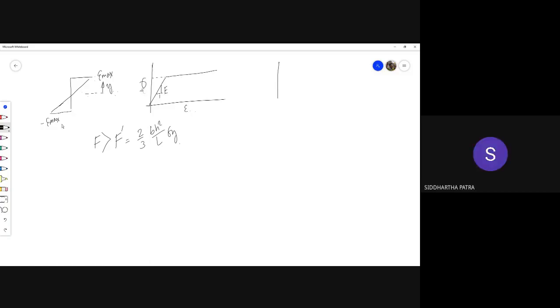You see, strain, whether elastic or plastic, strain changes with y proportionally. I mean the total strain, whether in elastic deformation or plastic deformation, it has to change proportional to y. Now, what about stress? Then stress would change with y exactly the same way it changes with strain, because you see, strain is proportional to y. Does that make sense?